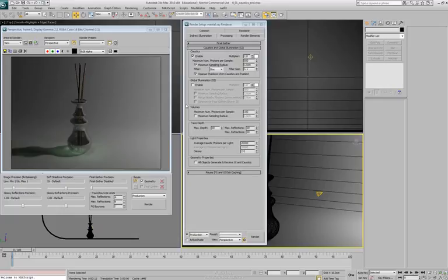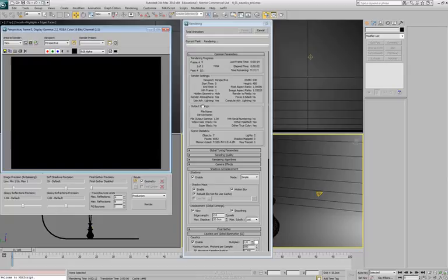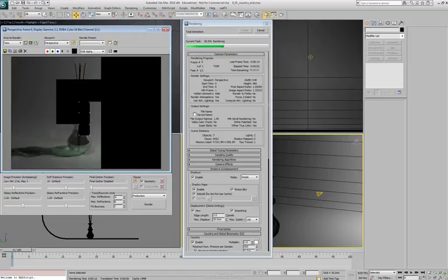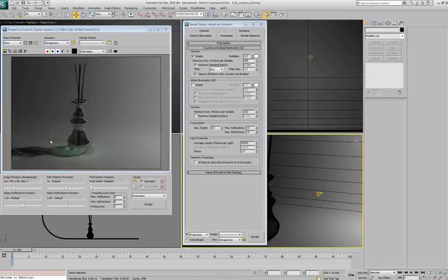So by doing this, the maximum sampling, this is the manual process of it. By taking it up to the 1.0, it's too much. So let's say we take this down to something like 0.1, we'll do a 0.2. And we re-render that. Now, by taking it down, we're not going to be smoothing it out as much. We're going to be trying to keep that a little bit cleaner, give us a little bit more detail. And it has given us more detail, but it's also left us with still being able to see some of these photons in here. It hasn't quite blurred them together very well.